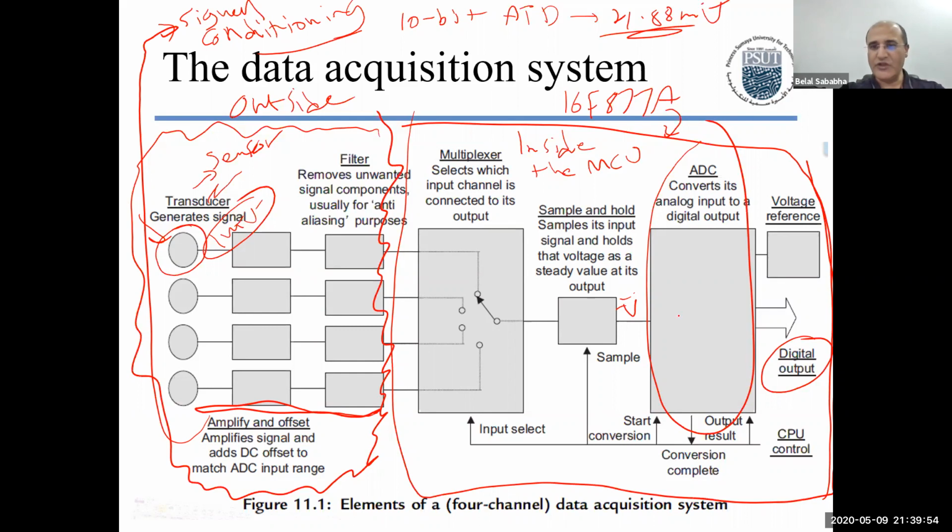And the voltage you can read here is positive voltage. So if you were in the negative part, you may need to add an offset or flip it. Okay. Then when you amplified the signal, you may have amplified some noise with it if it was so small. You may need a low pass filter, an averaging filter, which is a low pass filter, of course, or any other kind of filters.